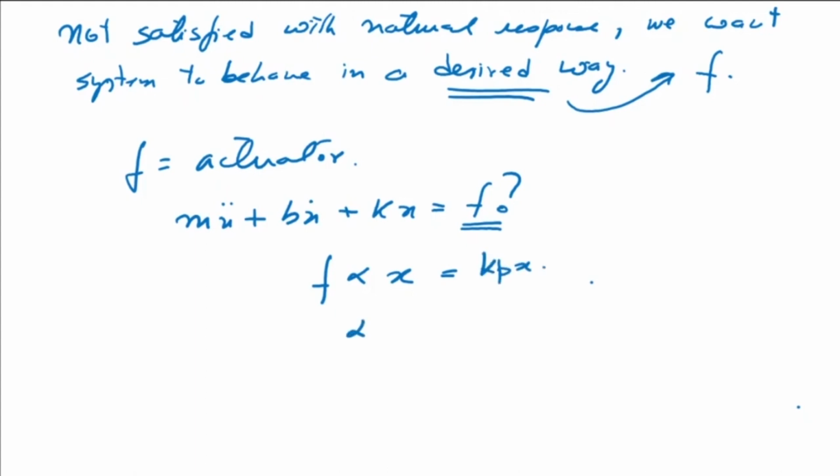It should also be proportional to the velocity, which is kv times x dot. If I put only the first term, it is going to overshoot the point and start oscillating. So there should be something that changes with time, and that is my kv times x dot.